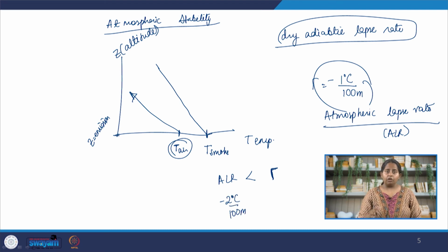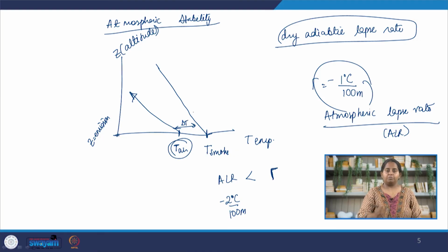reason. Now in this scenario, what is happening is that the thermal buoyancy, which is proportional to the difference between the temperatures, it could be T4, T2 or just del T, the thermal buoyancy of the smoke is increasing as it rises up. So what will happen is that thermal momentum of the smoke will increase as it goes up. Vertical dispersion will be very nice. So we'll have the smoke that is rising up will shoot up, will run up.